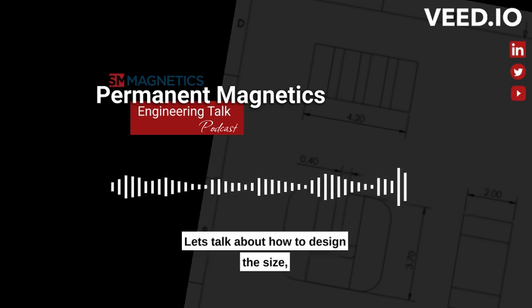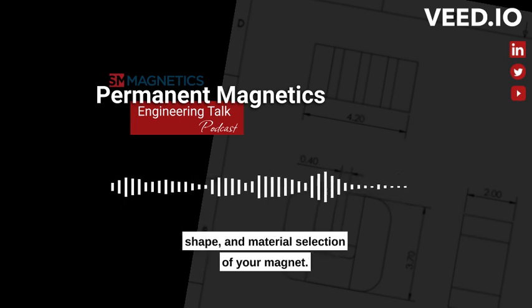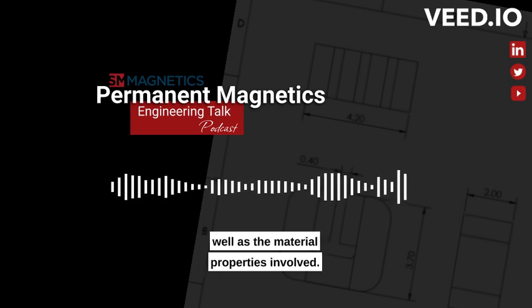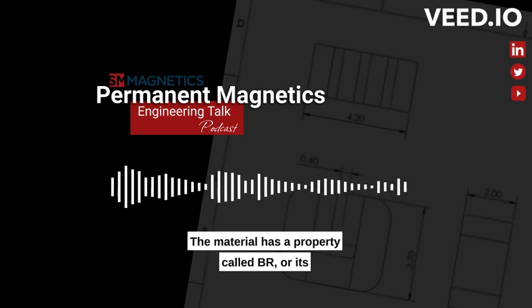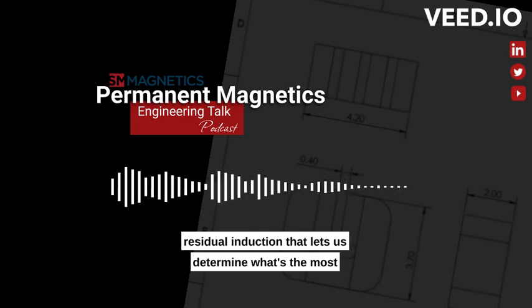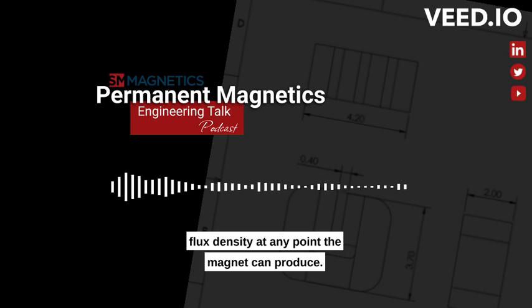Let's talk about how to design the size, shape, and material selection of your magnet. The size and shape are going to determine the magnet's actual output as well as the material properties involved. The material has a property called BR, or residual induction, and that lets us determine the most flux density at any point the magnet can produce.